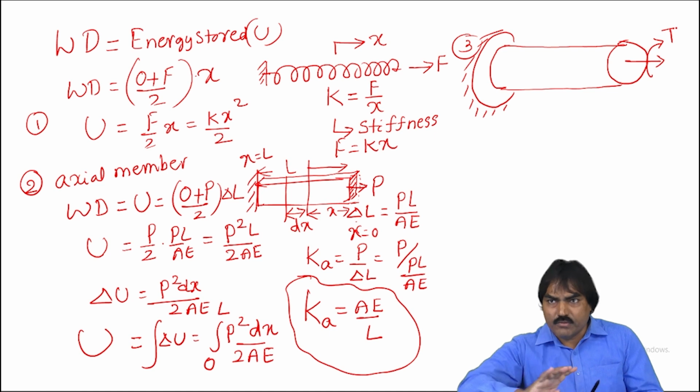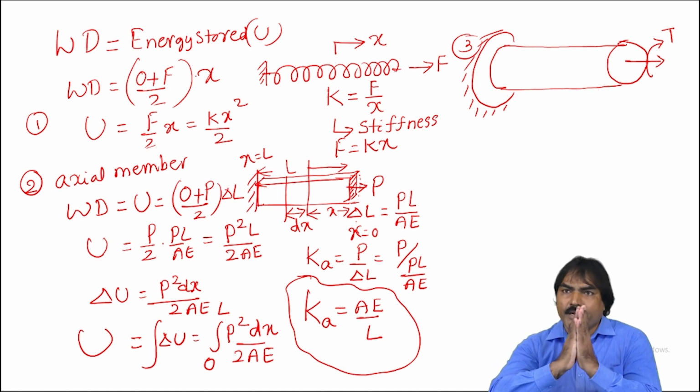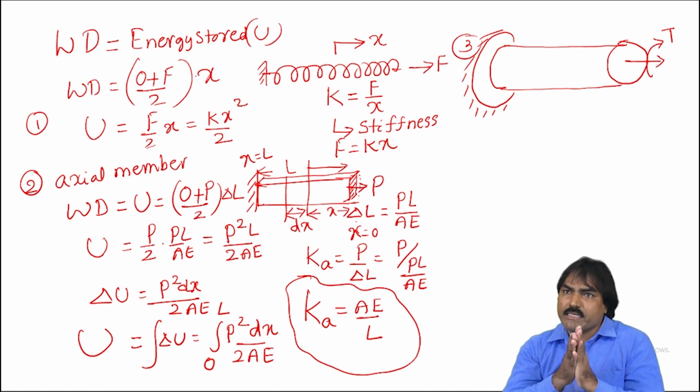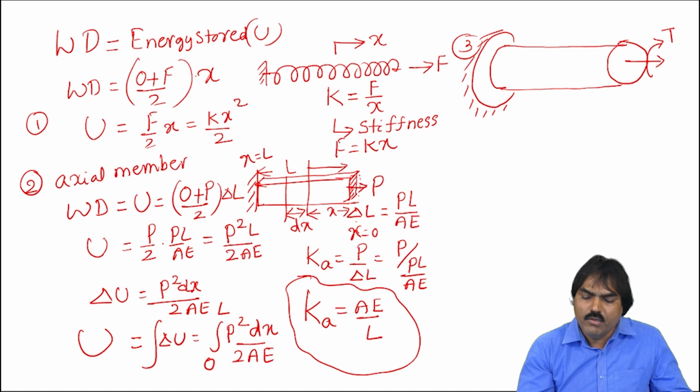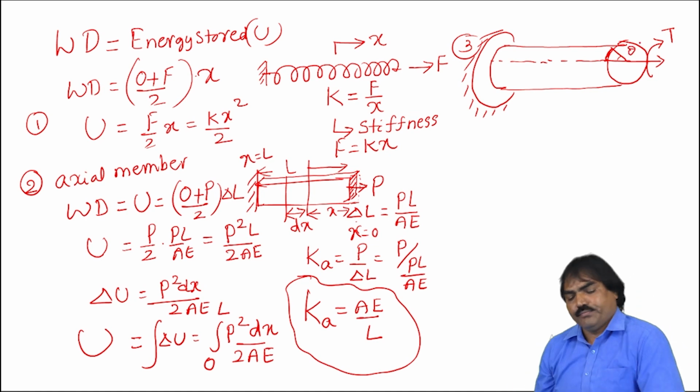So now because of torque, what happens? These cross sections of the shaft will try to rotate tangential to the surface, resulting in torsional shear stress. So that if I take a small element here, this layer will displace to this layer, so that the cross section rotates an angle theta.